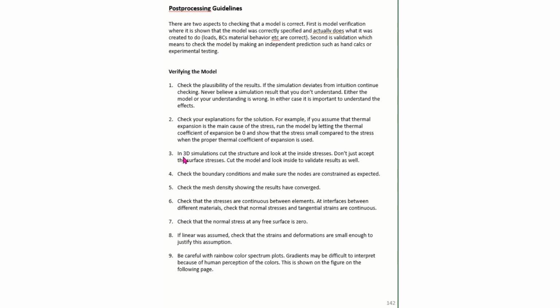In 3D simulations, cut the structure and look at the inside stresses. Don't just accept the surface stresses. Cut the model and look inside to validate the results. You will want to make sure you do this in all of your finite element models, and particularly your final project where you're looking at the stresses in a bracket. You want to cut that bracket and make sure that the stresses make sense inside the bracket.